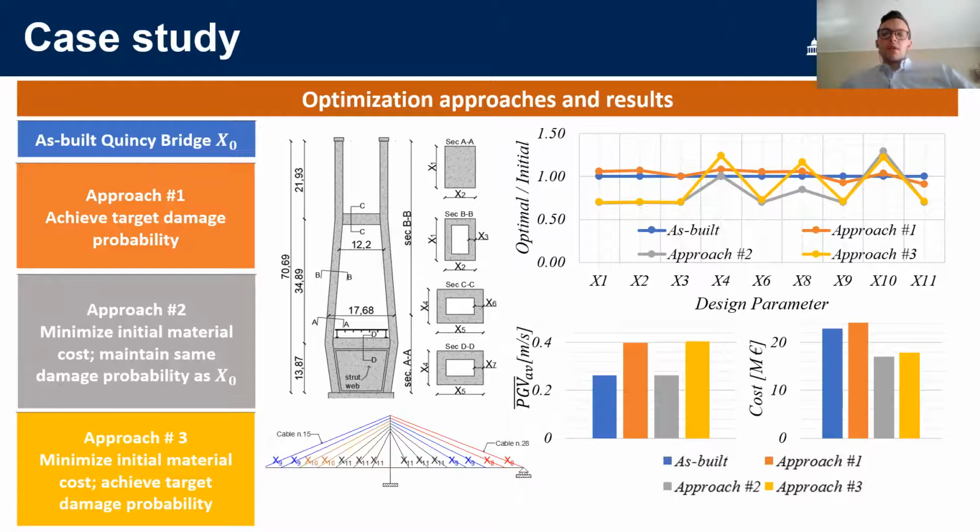And in the approach I'm trying to develop, we cannot use structure-specific intensity measures, for example the acceleration of the response spectrum at the period of the structure, because that will change in each iteration. So to conclude the answer to your question, it was because PGV has a higher correlation with the peak response of cable-stayed bridges and generally with the response of long period structures. Thanks a lot.